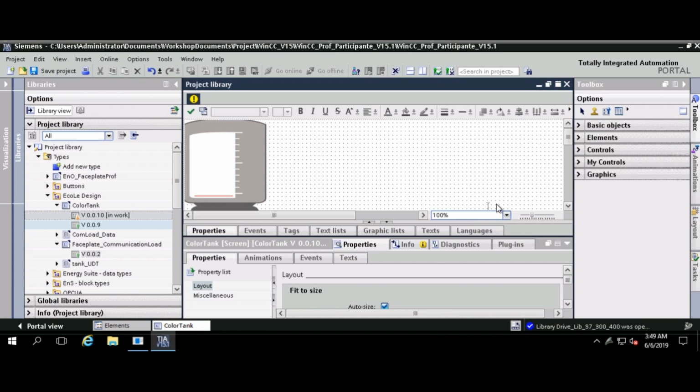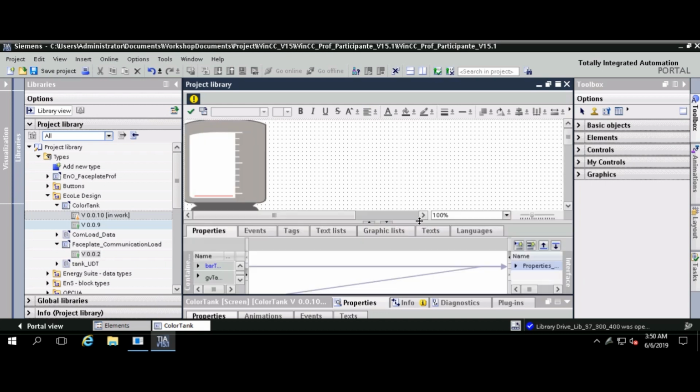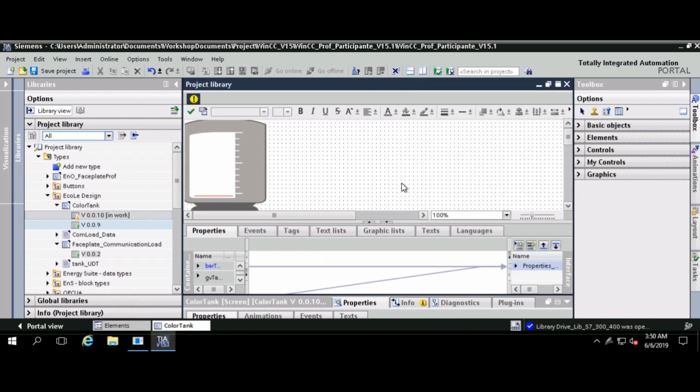In order to link the process value, or the property process value of the IO field, that's the right wording, to the interface of the faceplate, I go to General of the faceplate. There I have my process value property. And I just drag and drop it to the properties of the faceplate. And that's actually all I have to do in order to put the property to the interface of the faceplate. And I'm just going to name it again, valve state.